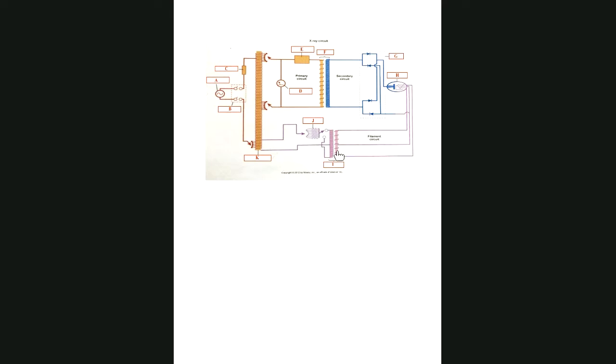You're going to have to recognize these symbols. So if you see just one set of windings, because of the location, you know, auto transformer gets power first, operates off of self-induction. I go over here, MA selector, this is a step down transformer. Where does it belong? In my filament circuit. This is a step up transformer. This is my high voltage transformer. It steps up from primary to secondary. So you have to recognize by number of windings what it does.